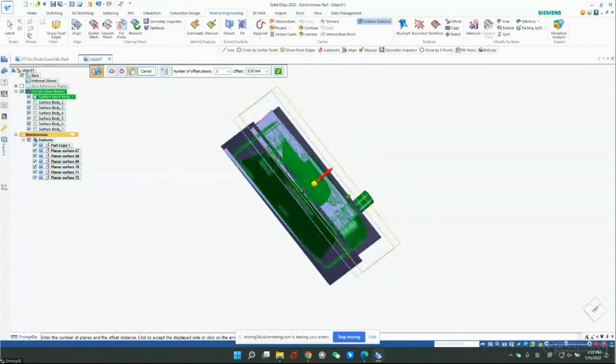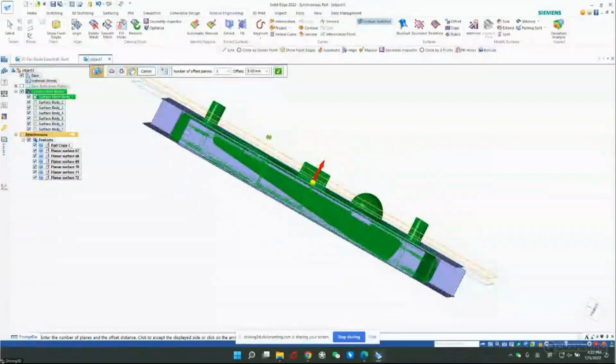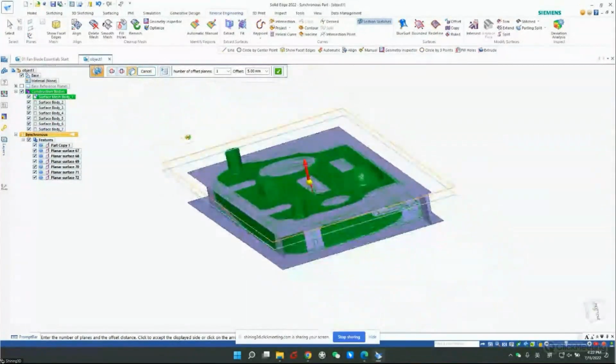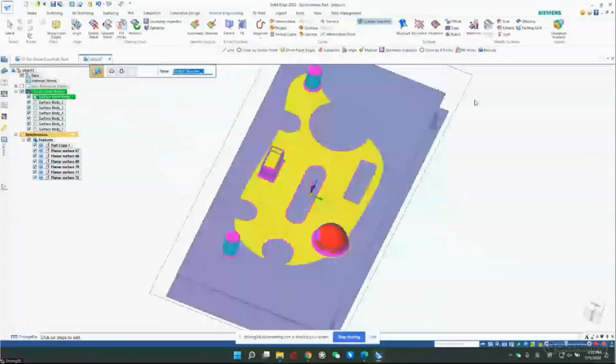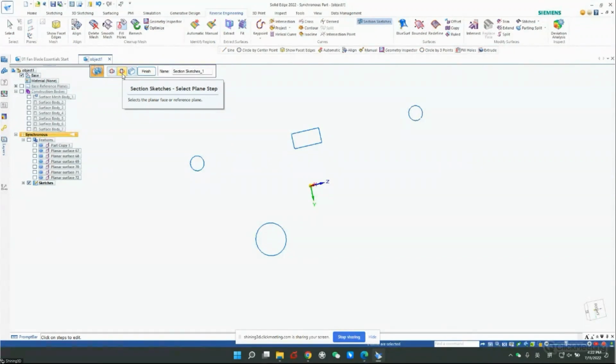You'll be able to see the preview on the software. So it's cutting the top 2 cylinders pretty well. And you click on OK. And if you turn off other features, you will be able to see that what it does is that it uses a plane to cut the scan data, and it will generate a sketch based on the intersection of the plane and the scan data. And like I said, you can do multiple cross-section cutting.